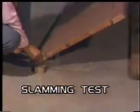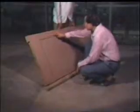Next, we come to slamming test. The door is hinged on one of the long edges and lifted 30 degrees to the horizontal. The door is allowed to drop under its own weight on a wooden rail. General condition shall be noted after every 10 drops. There shall be no visible damage after 50 drops. The slamming test is shown now graphically.